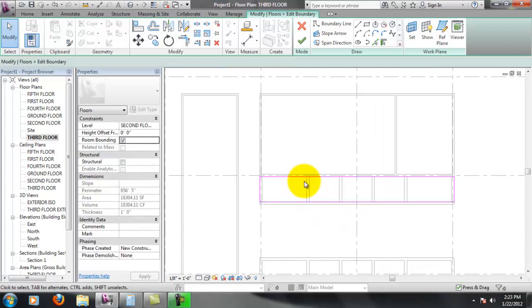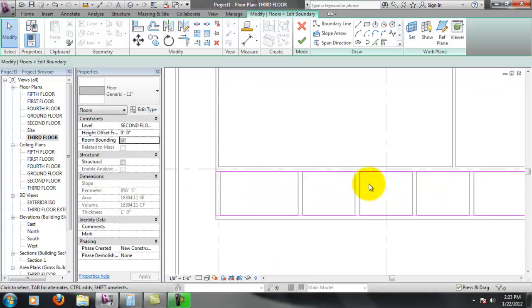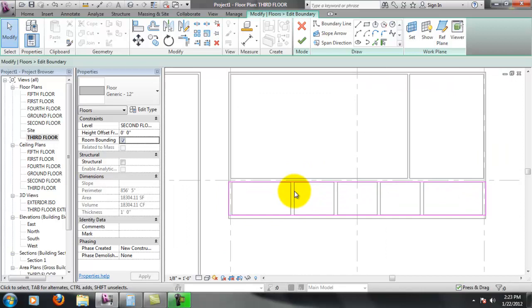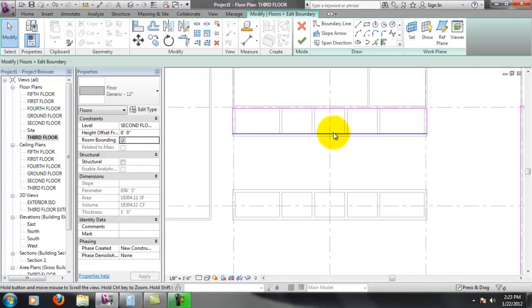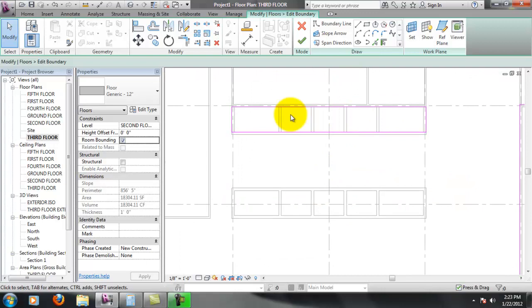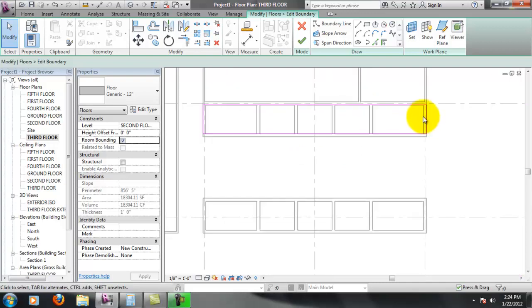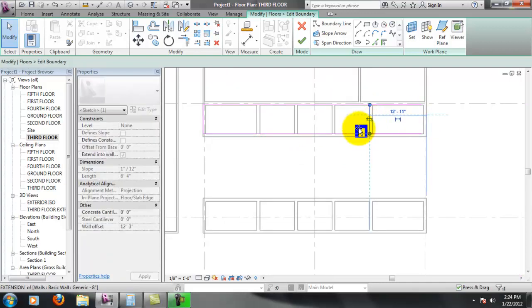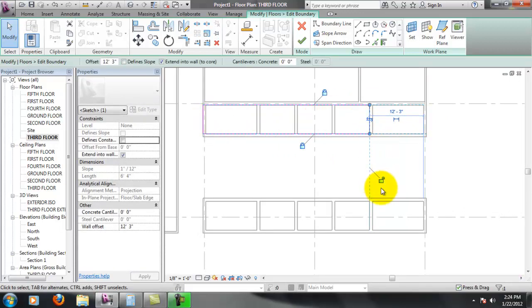Now these walls should technically go all the way to the ground, right? Because they're an elevator shaft. So in order to correct that, what we would actually need to do is change where these walls actually exist. So we'll leave them there for now. This opening doesn't need to be over here because the shaft ends here, right? So I'm going to lock that.